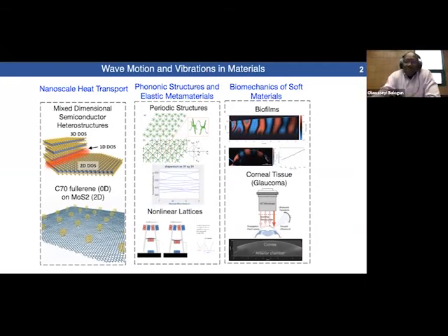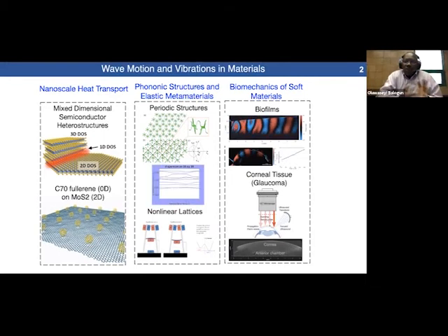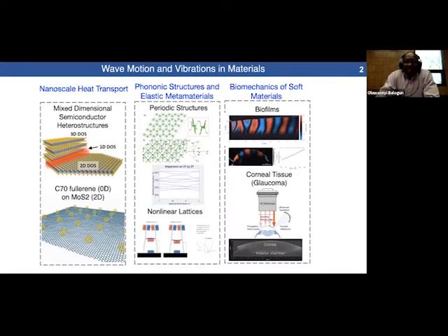We're also leveraging some of the ideas that we learned from atomic systems to replicate, say, the geometric properties in structural scales to create periodic structures and lattices that behave as metamaterials or phononic structures that ultimately can be tuned, for example, to serve as tunable mechanical filters or tunable mechanical diodes that allow you to control mechanical wave propagation in unprecedented ways. So we leverage things like bending, deformations, and nonlinear coupling between mechanical elements as levers in order to control wave propagation in these materials.